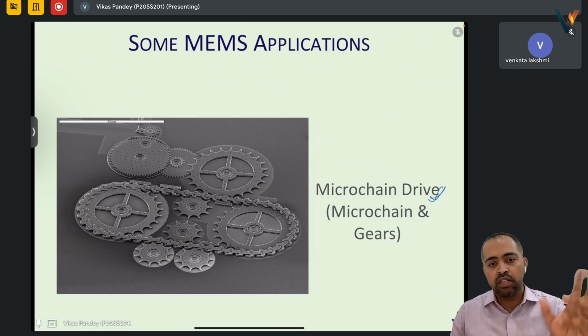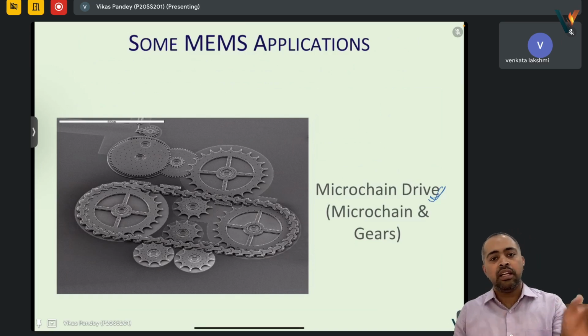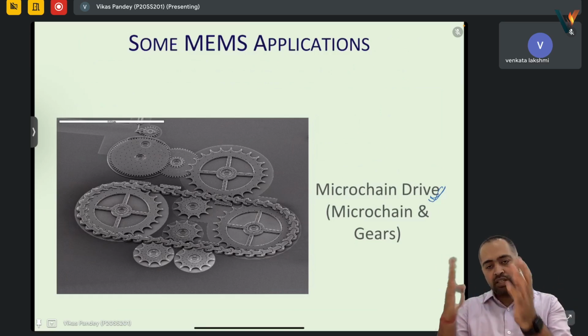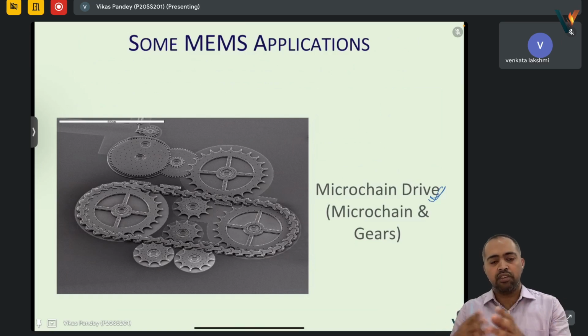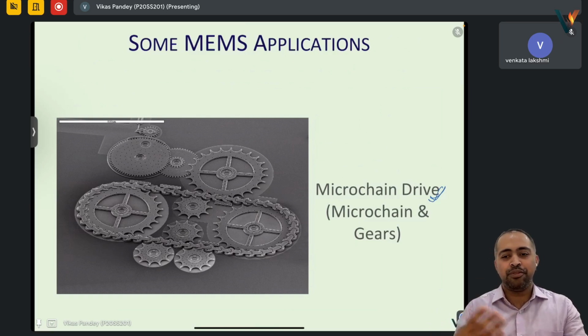That is controlled using MFC, mass flow controllers, and that is again interfaceable through LabVIEW. So when we combine this system, we have created one system based on LabVIEW in which we can control the amount of gas as well as take the output from current, and a combination of this, a table kind of structure, an Excel CSV file, can be output. We are also using LabVIEW, but not very frequently. We are using it as an application, you can say.